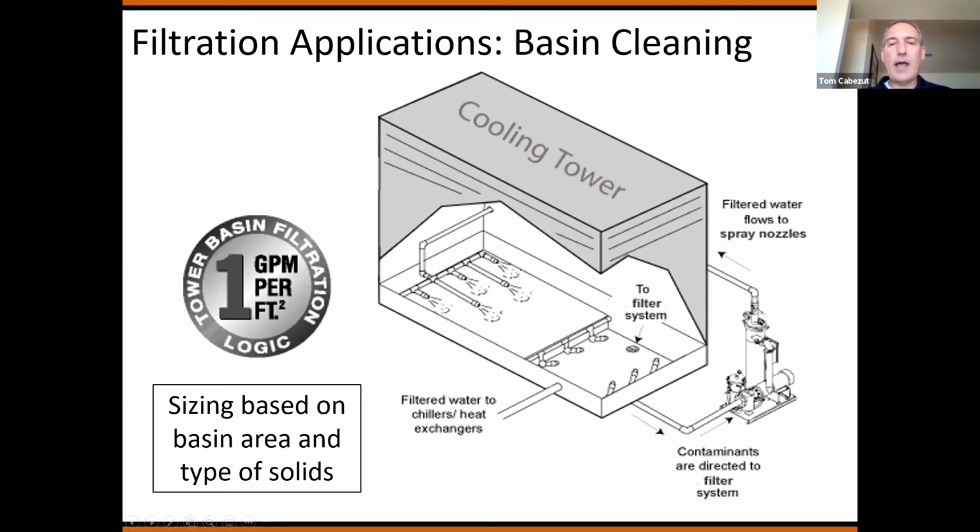And like I said before, you need to make sure that whatever piping, if you're ordering it from the factory, Marley, BAC, or Evapco, just make sure again that the piping flow rate requirement matches the filtration skid that you're applying to it.